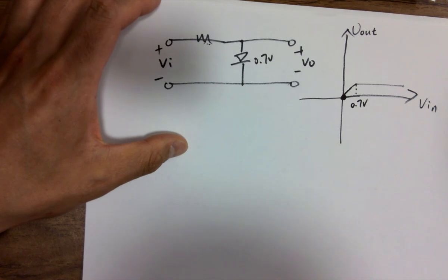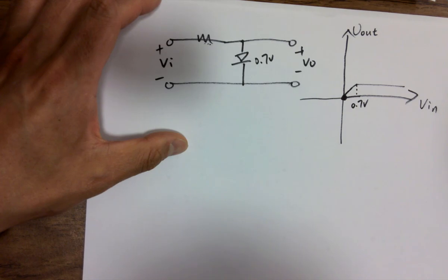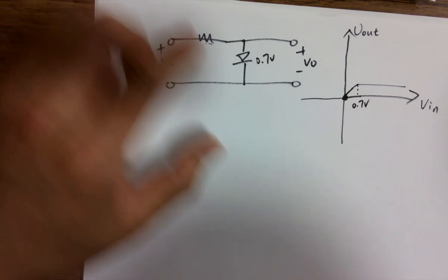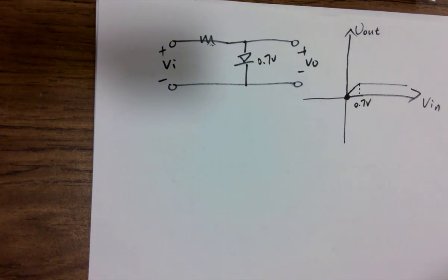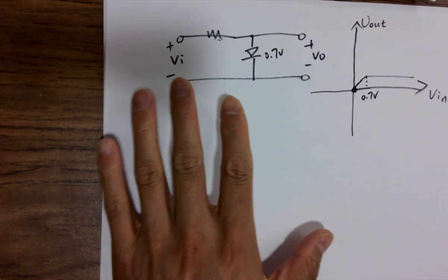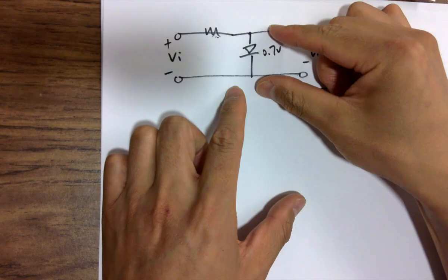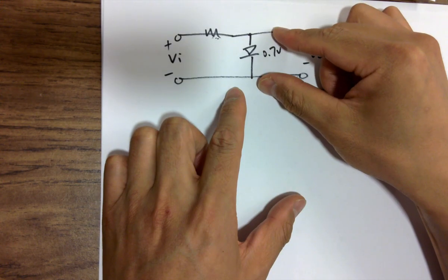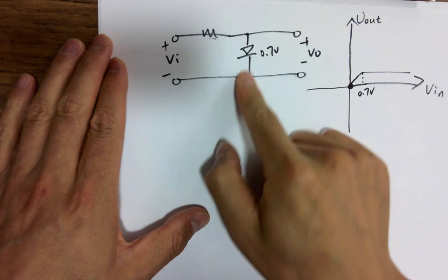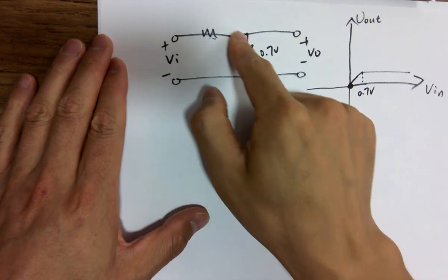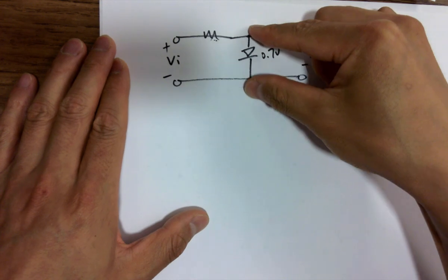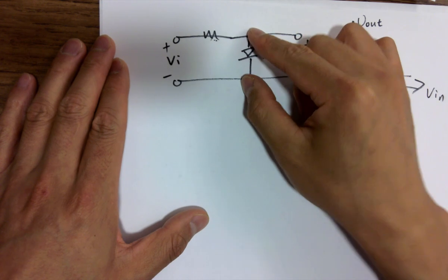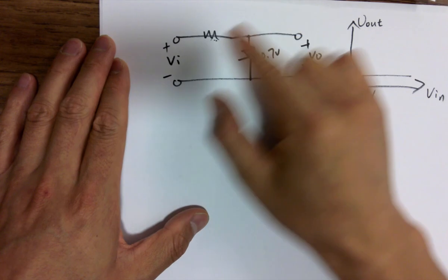Does it increase the resistance of the diode, because you get wider depletion, or is it shrinking? No, this is not changing anymore. It keeps at 0.7 volts. What's happening is the current runs this way, because the power supply has a ground loop. If you increase the voltage, and this is fixed at 0.7 volts, the only place you can drop the voltage is actually here.